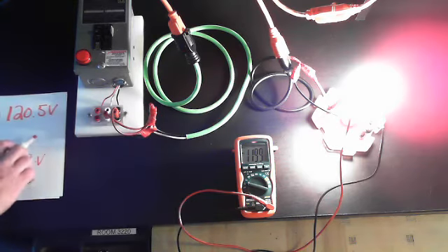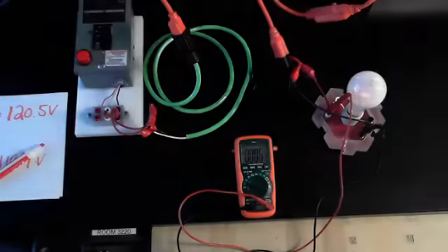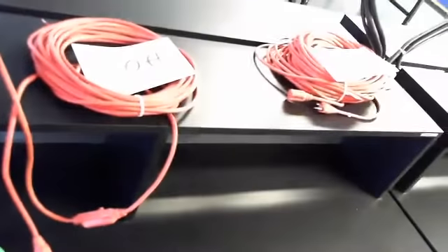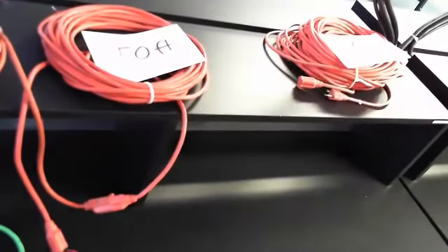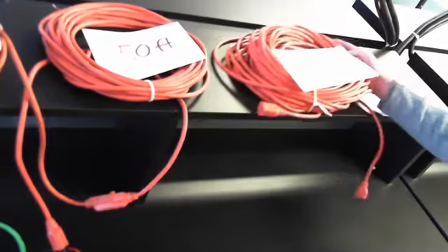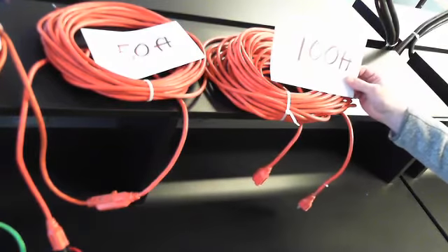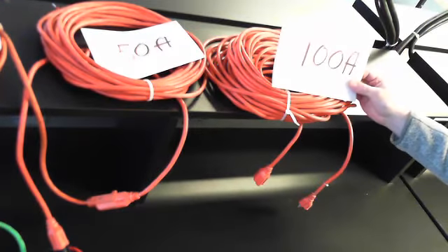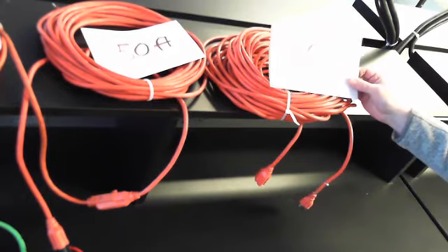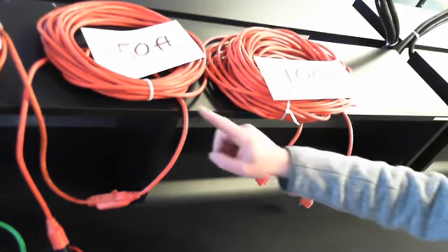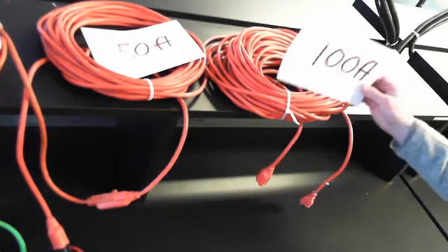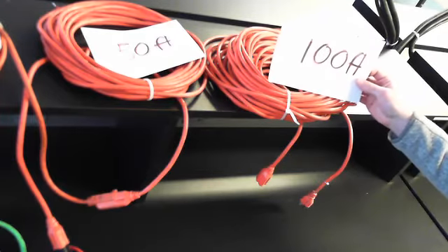And then what we'll do is look at what if we added another extension cord. So now we have 3, but this extension cord is a 100 foot. So I'm doubling again, but I'm only going to have 2 additional connections, right? With two 50-foots, I have 4 connections. I'm going to have another 100 feet, but with only 2 connections.